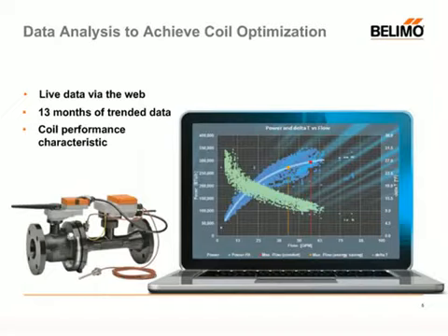And what that allows us to do is suggest a delta T set point based on your current system conditions. This is a very powerful tool, and it's very, very user-friendly to help optimize the system. What this actually does is allow you to trend the data within your system, and we're going to walk through how each one of those trending elements works, take the system, pull it into our tool, and look at a nice, very smooth delta T suggestion of how your system should be performing.